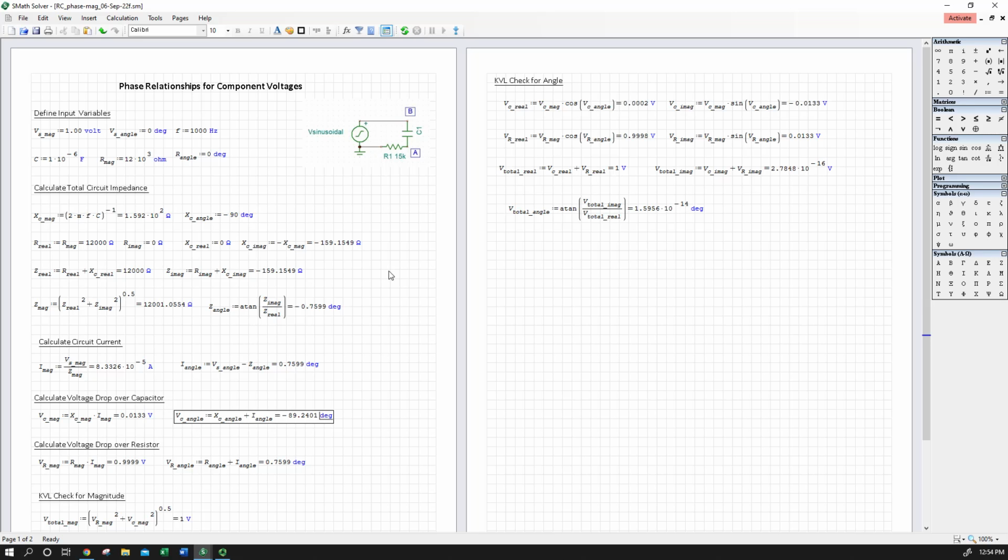And a small review of our polar value mathematics, switching between rectangular and polar expressions when we need to either multiply or divide to apply Ohm's law, or add and subtract to combine voltages or impedances for our components in series. I'll add a note that we didn't include any parallel configurations.